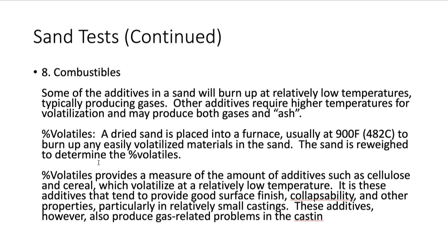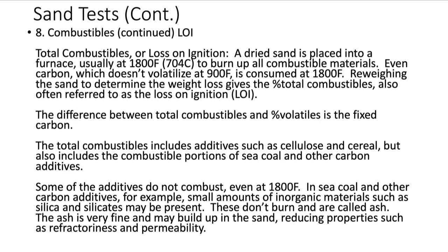Collapsibility and other properties are proportional to these things. Now, sometimes we want to find out the total combustibles. Okay, so there's other things that burn up at higher temperatures. So we do this at 1800 Fahrenheit. So it burns up all the combustible materials, even the carbon. Okay.